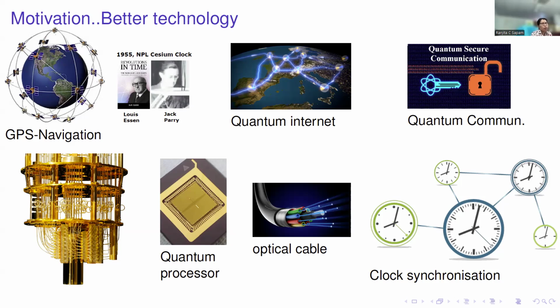The optical cables lying underground are made for 1550 nanometer, the telecom wavelength where we communicate in the telephone or internet. The wavelength of light they use there is 1550 nanometer, so it is good for that particular wavelength. If I want to send another wavelength, let's say 780 nanometer, it doesn't propagate. I lose all the signal. So signal loss is there. That's why we need amplifiers and repeaters. The quantum repeater is another research field, another topic people explore while developing quantum technologies.